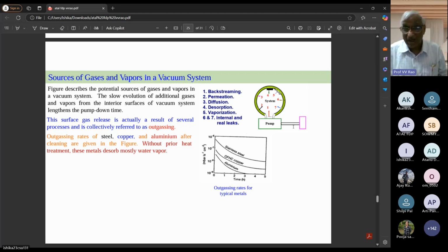Whereas stainless steel is weldable. And aluminum is not weldable for another reason: it's a good thermal conductor. Whatever thermal energy you are giving will be conducted away very fast to the remaining aluminum. So these are all very important. There is a lot of metallurgical research going on in the material science and metals departments on advanced materials. There, how do you weld?